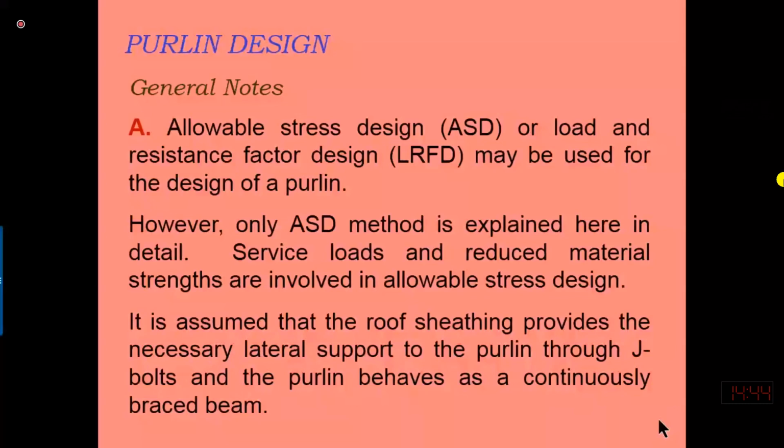So then all these roofing sheets and others are connected with the purlin. It means that all types of load are transferred at the purlin from the roof sheeting. So what the purlins are doing is they transfer all load in terms of point load or concentrated force at a panel point or at a joint.